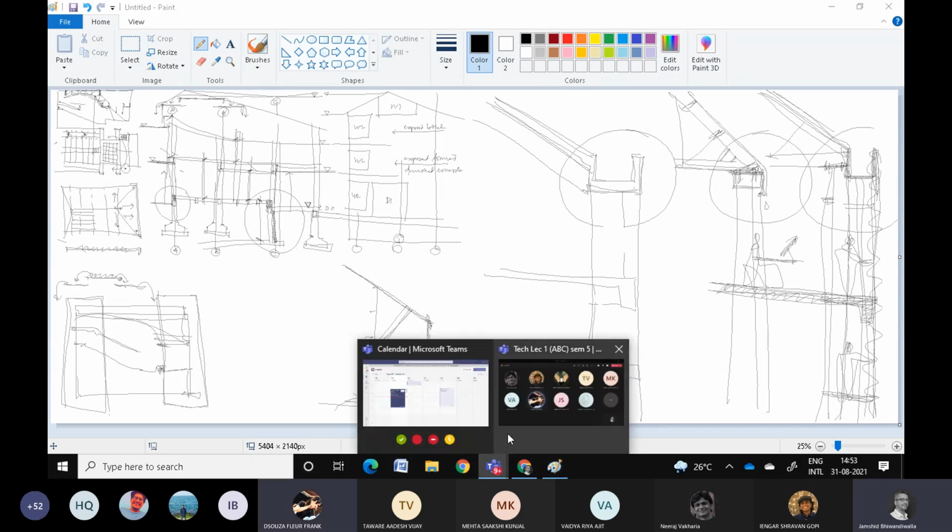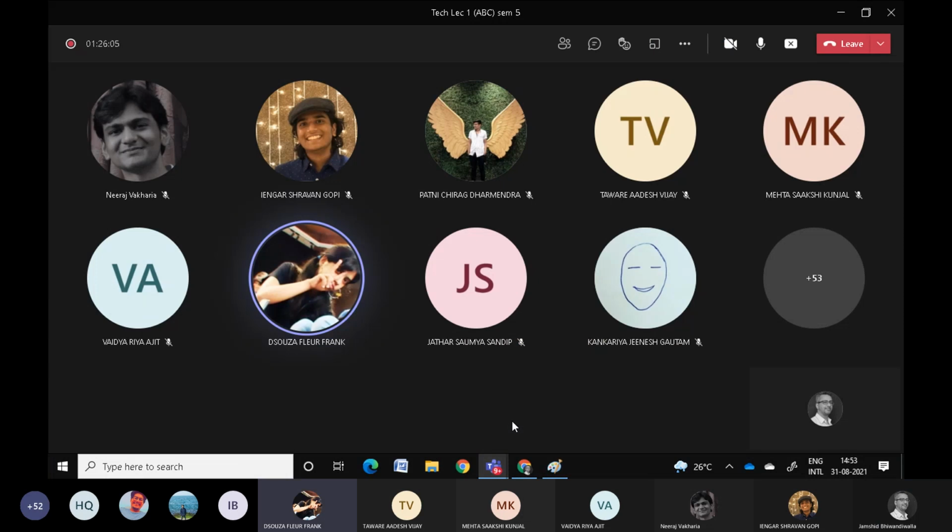Yes, but if it's just a plain metal facade, is it a safety standard to have that, or can we not? No. A metal facade is just a metal facade, though you don't need any walkway. All this cladding that you see usually has a framework behind that does not allow you to actually access anything behind that framework. No. So if we were to attach it to the wall, which is recessed, we can use brackets or something and attach that specifically.